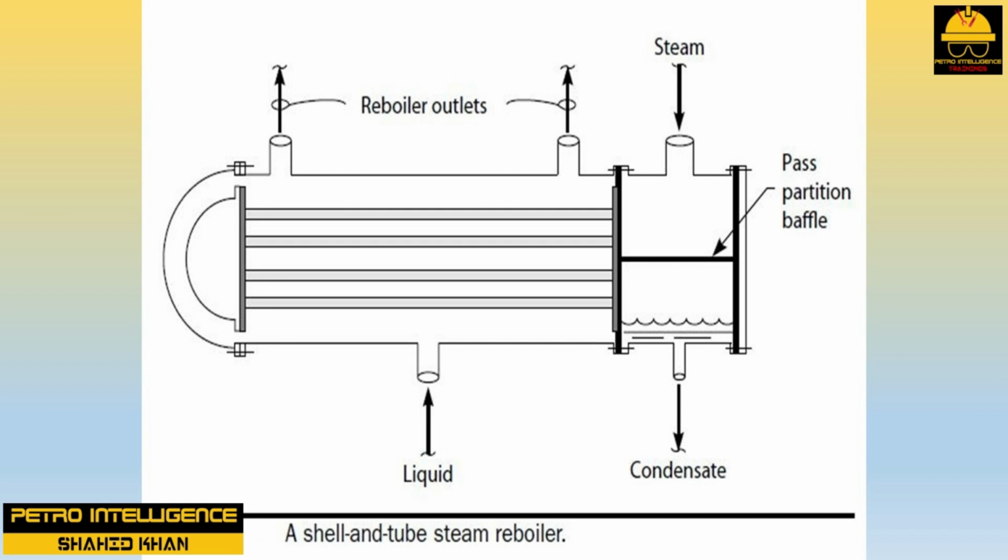Heat exchange provided by sensible heat transfer is improved when velocities are higher. Especially when the heating fluid is on the tube side of an exchanger, sensible heat transfer rates are always increased by high velocity. Heat exchange provided by latent heat transfer is improved when velocities are lower. It is my experience that this loss of heat transfer at high velocity is quite large when steam is flowing through the tube side of an exchanger. Theoretically, this happens because the condensing film of steam is blown off the tube surface by the high vapor velocity.